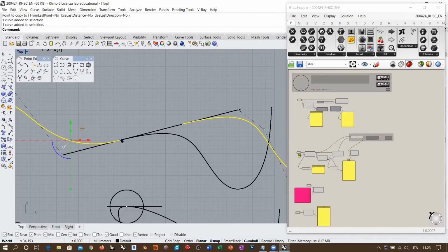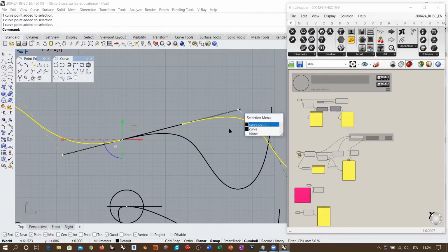In order to end here and have this tangent, I need to define the position of this control point and this control point here. So these last two control points define the final tangent for our line, which is aligned with this tangent line. And then I have the second line starting from another point, and with the second point aligned here in order to have the same tangent.